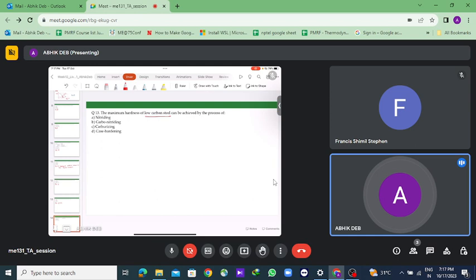Actually, yeah, the statement was like, to be most effective, the steel must contain certain alloying ingredients such as aluminium 0.85% or more and chromium 5% or more. Yeah, that's what I'm saying. That for more effective, see these, they not necessarily form the compounds, but they form interstitial compounds, or they might form precipitation hardening in some cases.